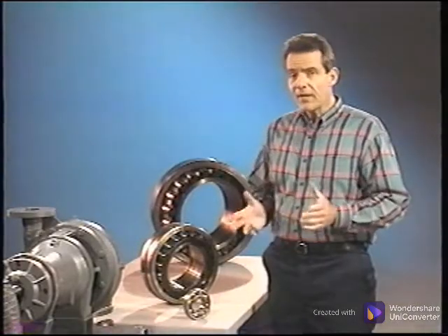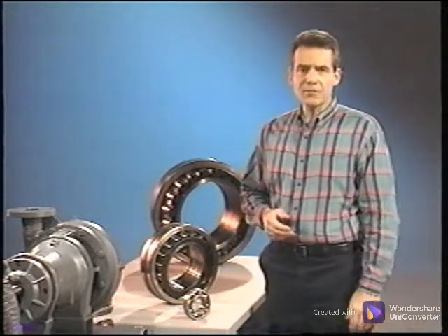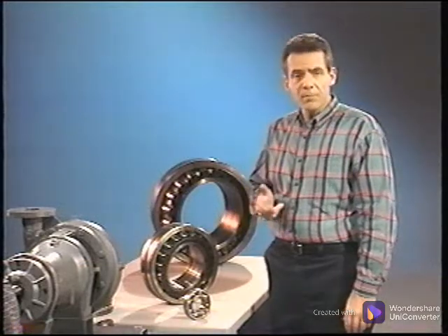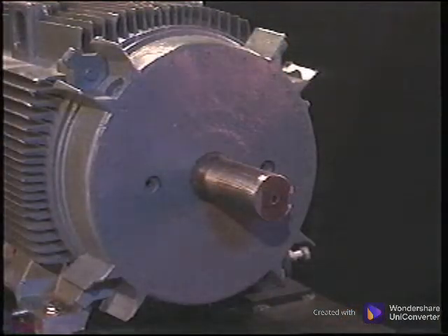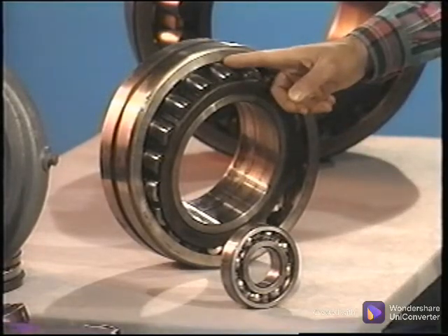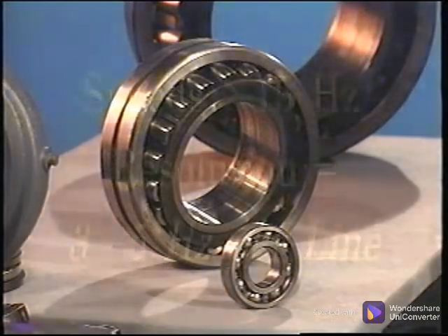Again, realize that these are idealized for the bearings only. No other considerations have been made. Practically speaking, both of these would probably be modified. If the small bearing were in a motor, then rotor bar problems would be missed if the maximum frequency were only to 40 orders. If the large bearing is turning very slowly, we may be interested in multiples of gear mesh that may be outside this range.